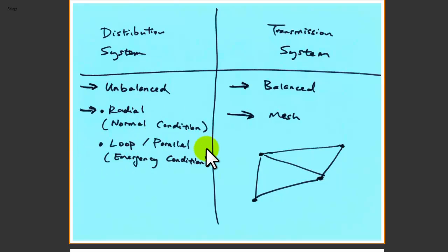So we are going to explore different techniques to run a load flow analysis. In the transmission system, I'm sure you heard about the Newton-Raphson, Gauss-Seidel, and fast decoupled techniques. Those are the techniques used to handle the Y matrix, whereas in the distribution system we are going to simply deal with the 3x3 Z impedance matrix.